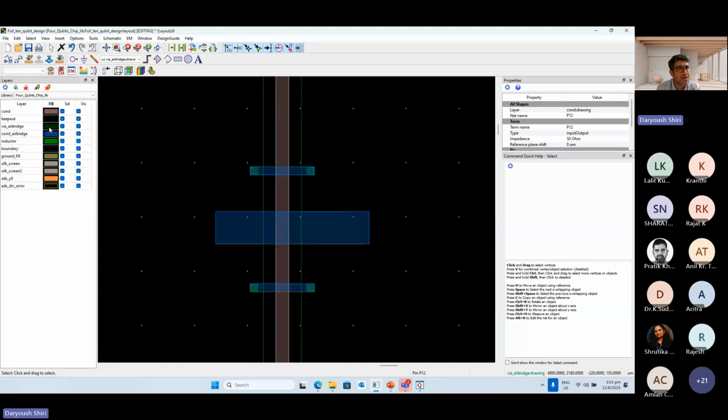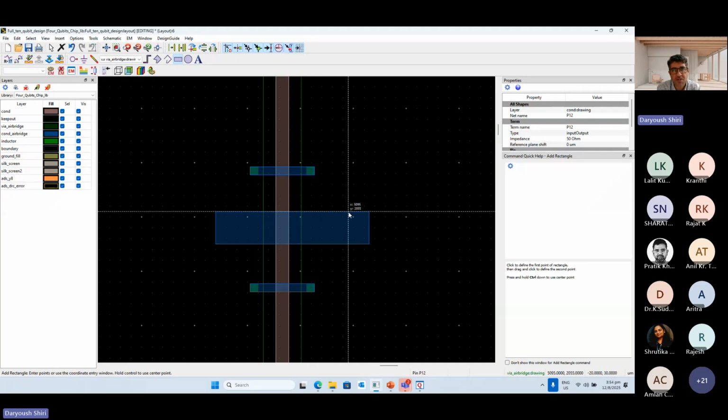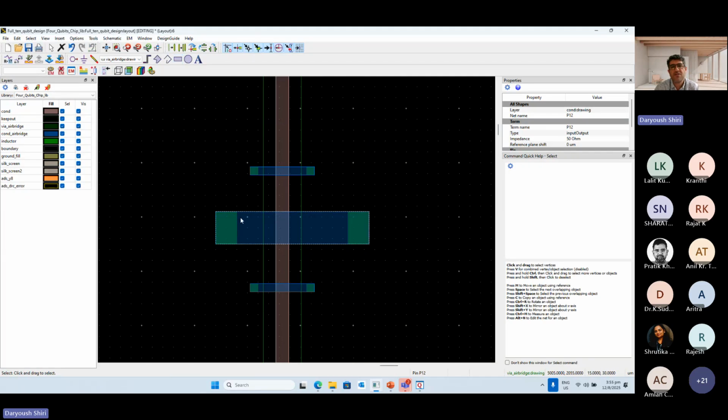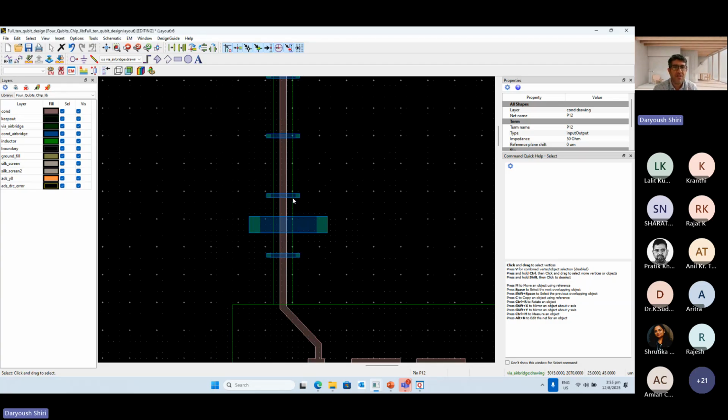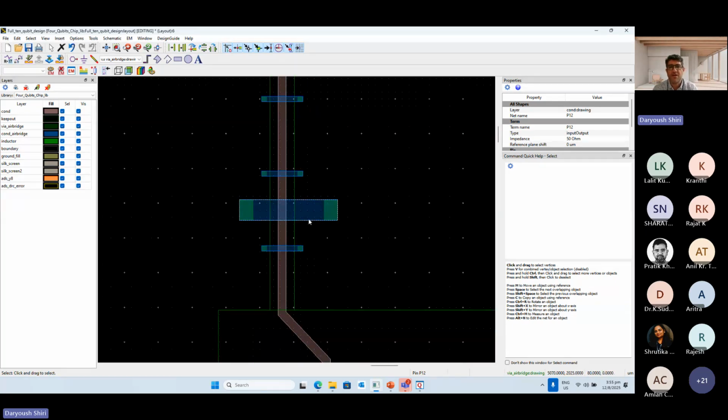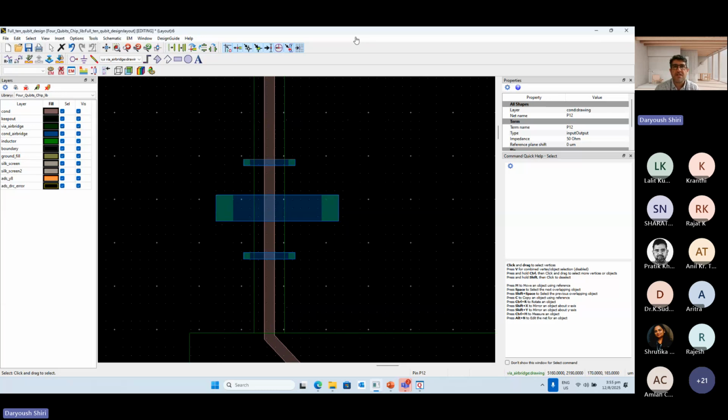The footprint of the air bridge also needs 2 pieces of metal, telling the layout that those footprints are attached to both grounds on both sides of the CPW or whatever you have. So if you are not happy with the air bridge or its period or size, you can design your own in the layout wherever needed.